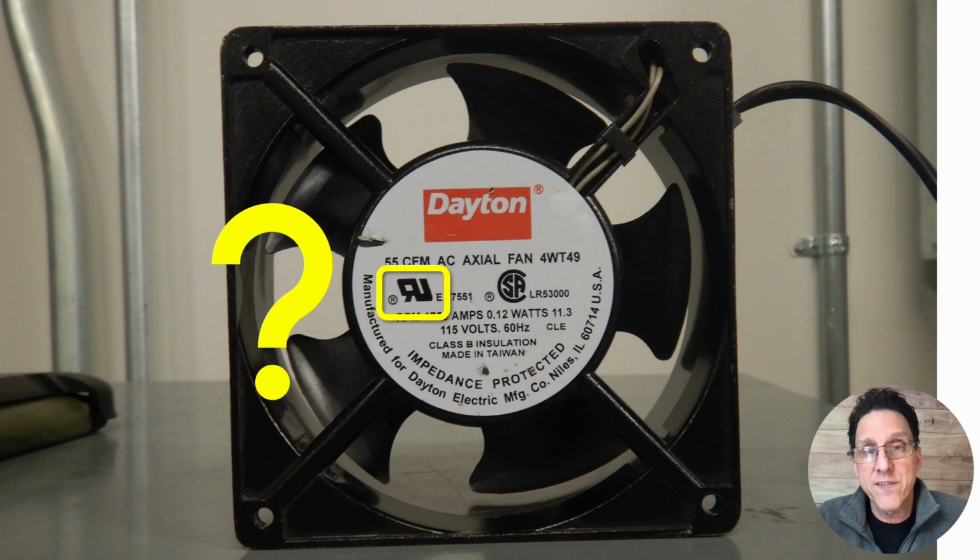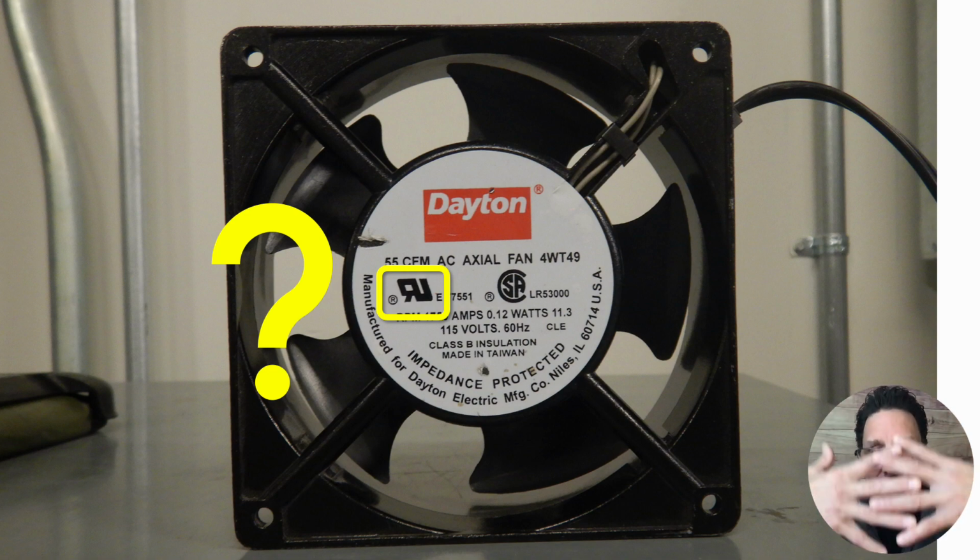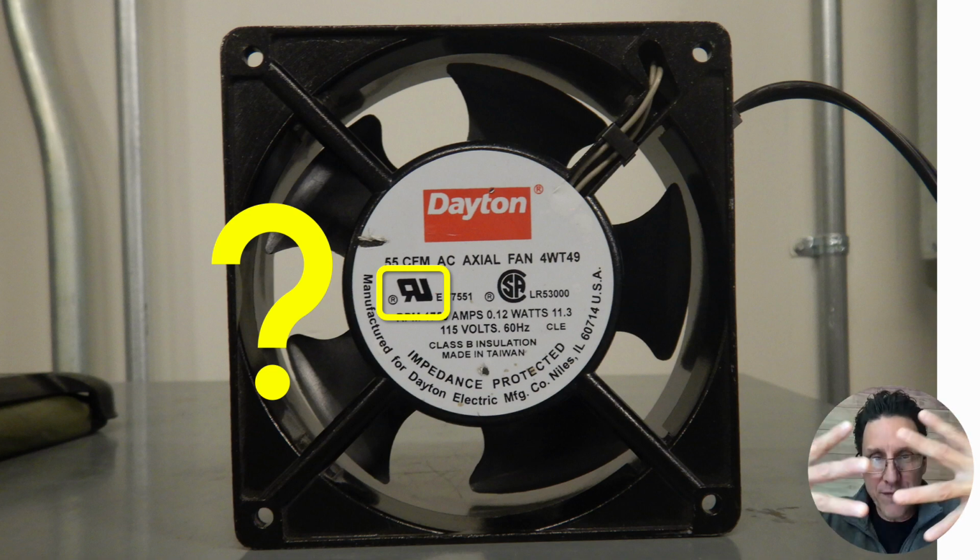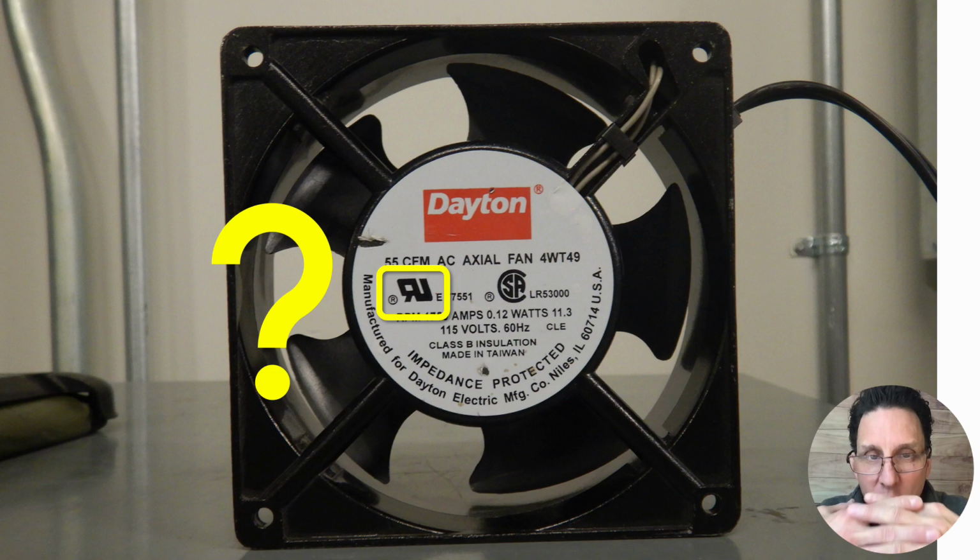You've got to move that piece of equipment. Don't plug it in there. Put it somewhere else where you can put a receptacle in that is not required to have GFCI protection. So, no, manufacturer instructions don't supersede the code or allow you to set aside the code requirements. That is not true at all. They both go hand in hand. Manufacturer instructions and the code have to work together, right?